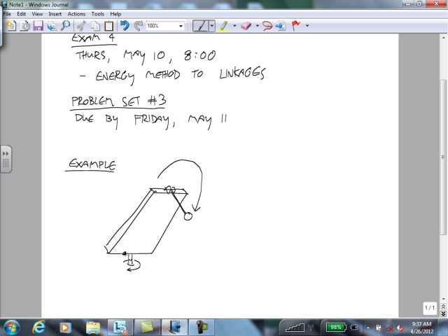So where do you fix your coordinate system? What you have to recognize is that the motion of this arm is a simple circular motion if your coordinate system is riding on the plate. If you do anything else with your coordinate system, then the motion of this ball isn't a simple circular motion. So that's why you need to recognize that there's two rotations here. One is a passenger on the other rotation, and you want to put your coordinate system fixed to that primary rotation.